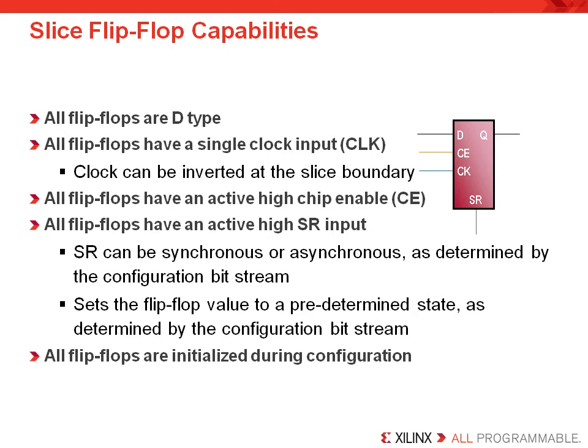Now, all flip-flops have a clock input that's denoted by the CK port. The clock can be inverted at the slice boundary as well, with that inverter being locally located. All flip-flops have an active high chip enable. So you'll want to be aware that if you design with an active low chip enable, then that will require an extra inversion on the lookup table output.